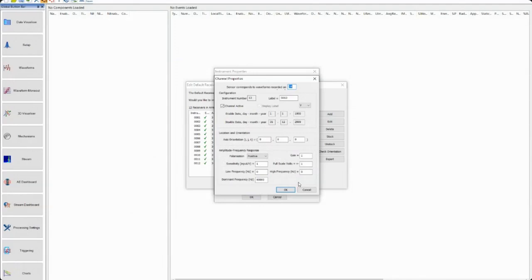It's not very usual to have more than 3 axes in one seismic station, but there are cases in which we have a calibration channel, a calibration sensor added to it. Or in some cases, it's more research type, but some companies supply this, combining an additional sensor that, for example, combines geophones and accelerometers, so that we can cover a broader band. So it's basically just the capability of InSite to take up to 4 traces per instrument, although it's not an usual setup.